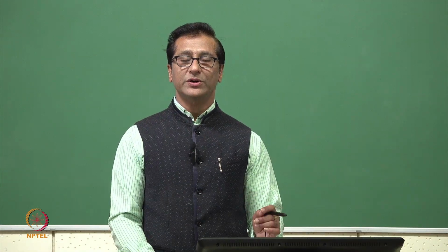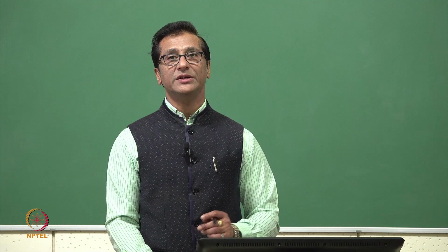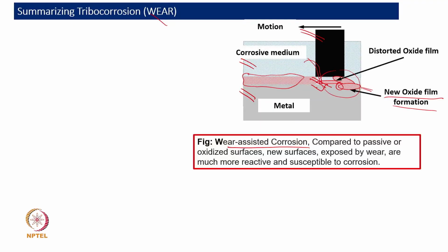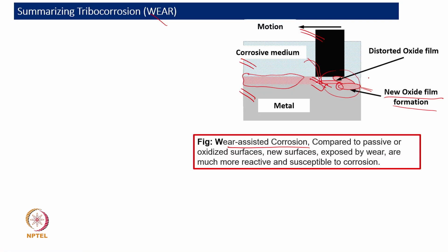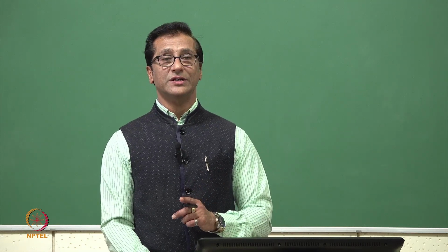Because of the wear phenomena, this oxide layer, a protective layer, got removed from the surface. Now because of that, the corrosive media gets ingressed into it, and that is creating more and more corrosive product which is brittle in nature and can also get removed easily. So now here the main difference comes. Quite possibly, corrosive media reduces the friction but increases the wear significantly.